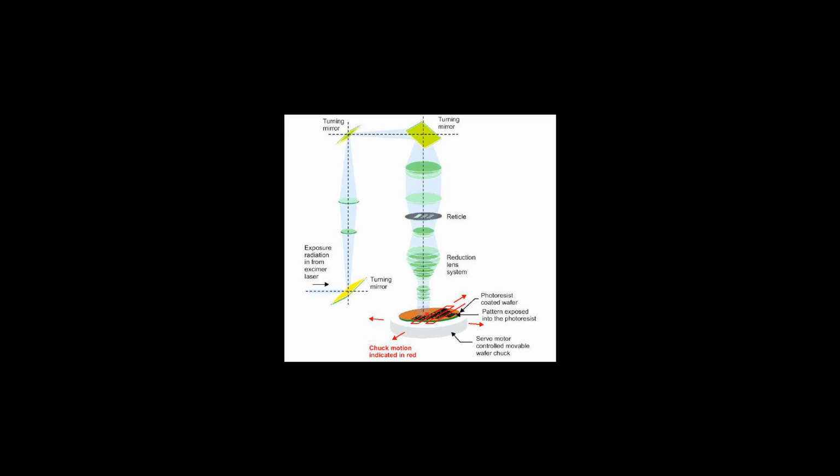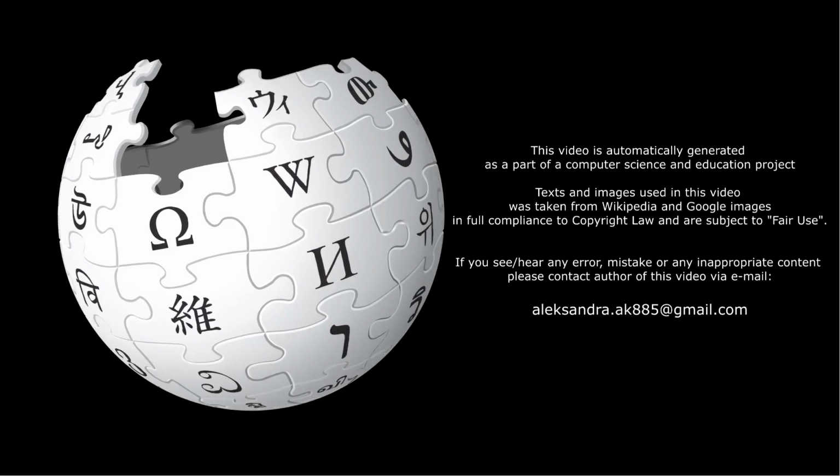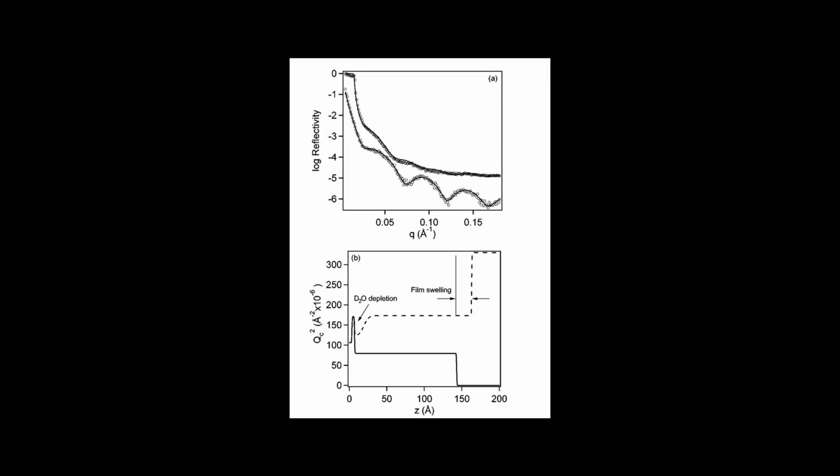The actual resist-water contact time in any given exposure area is minimal. Hence, the main concerns for defects are water left behind, watermarks, and loss of resist-water adhesion. Air gap, the hydrophobicity of the surface and the water delivery and removal method are therefore the key areas to address.